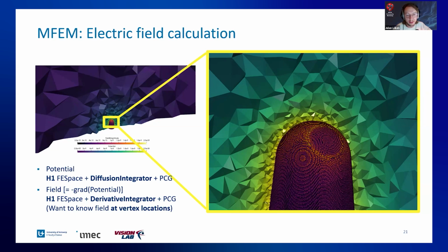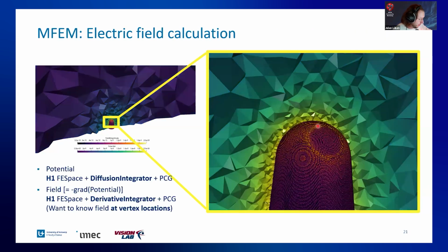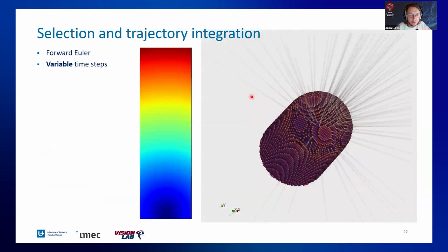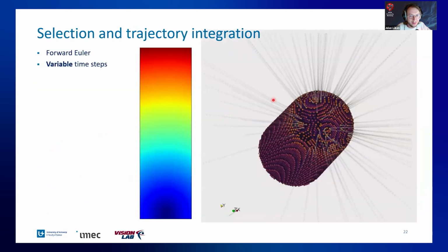Now when you look at the figure, you can see that the most protruded atoms have a larger electric field, which is realistic, and the highest field we find at the intersection of the surface and the material interface, which, if we remember, was like a circle on the surface essentially, and we can see that this circle is a little bit brighter than the rest. In the background, we can see just the electric potential because the field is almost zero everywhere. In comparison, it's relatively small, but it's not negligible. So that's the problem here.